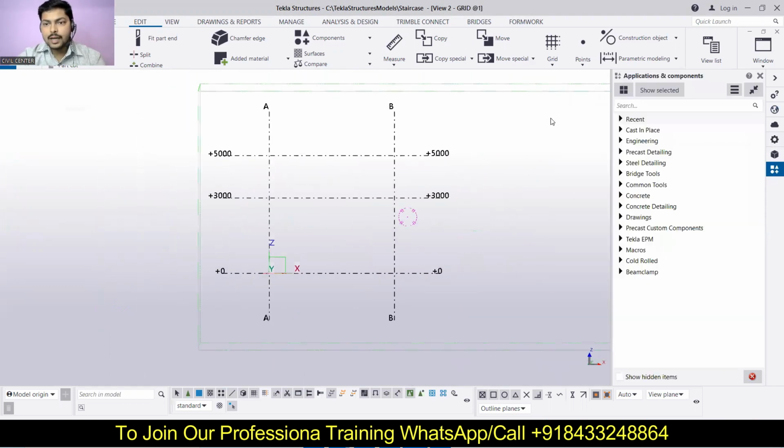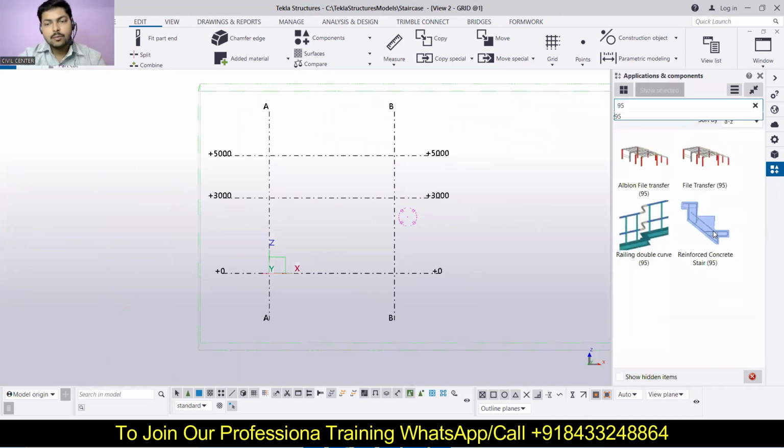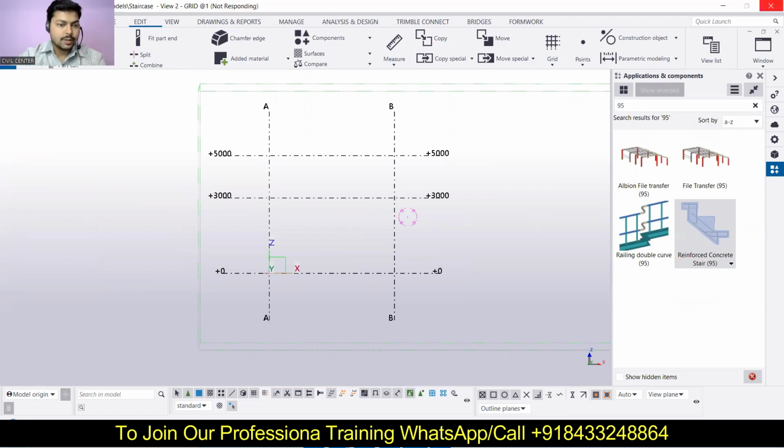Now we have to go to the application and component box, and there we have to look for the application that can model the staircase. So we have this reinforced concrete stair, and you can also type it as reinforcement application number 95. Just click over here and then select a point. You can see we are getting an option of pick position. So all we have to do is pick the position where I want to apply this. First I will pick the position, then I will pick the end position, and after that I will click on the middle button of my mouse, and that will be done.